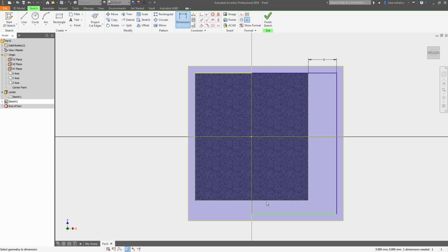And you can see this hanging out down here. I want this line to line up with this exactly. So I'm going to use a coincident constraint from this point to that line. So you'll notice the geometry changes color. In the lower right-hand corner, it also tells you that it's fully constrained. So Inventor knows when you still have to add either additional dimensions or constraints. So keep an eye on that lower right-hand corner as you're creating your sketches.